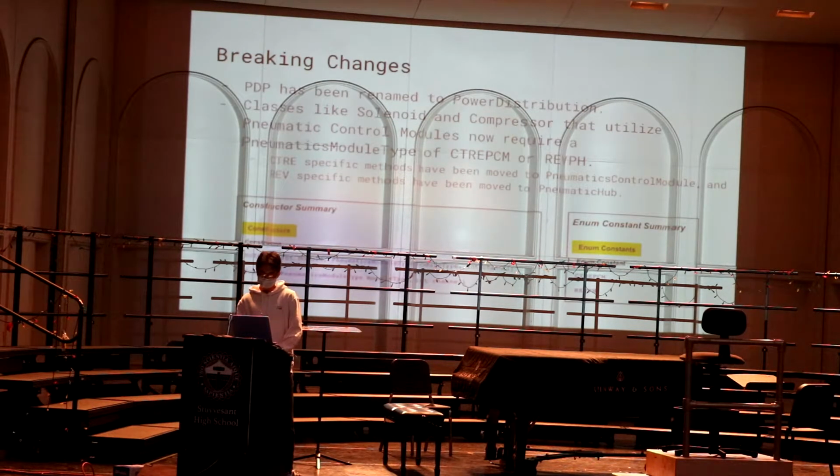The breaking changes, there are a lot of them, I think. The PowerDistributionPanel has been renamed to just PowerDistribution, and classes that utilize the pneumatics control hub, like Solenoid or Compressor, now require you to specify what type of vendor provided the solenoid or compressor.